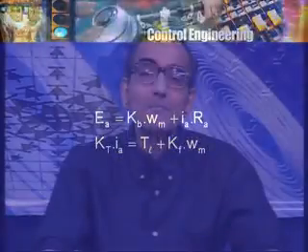As you can see, looking at the magnitudes, 230 volts, 210 volts back EMF, 20 volts armature drop. If the supply voltage goes down by 10%, the armature term, which is small anyway, the back EMF will go down by nearly 10%, and therefore the speed will go down by nearly 10%, not exactly 10%, could be a little less than 10%, but it could go down to that kind of an amount.